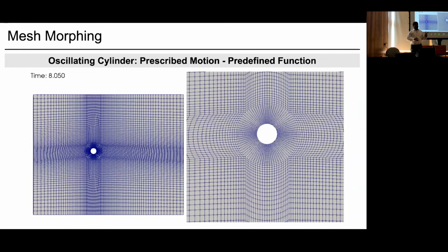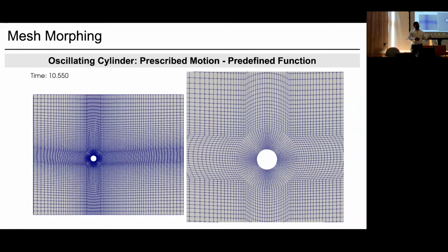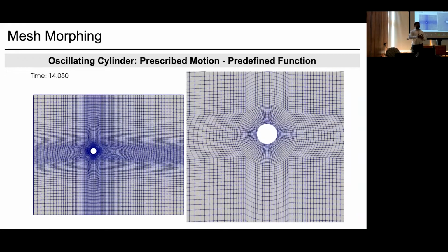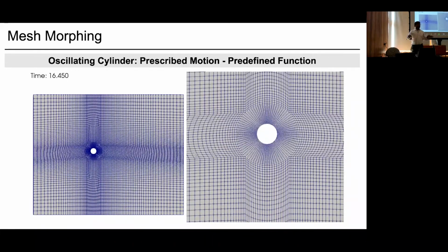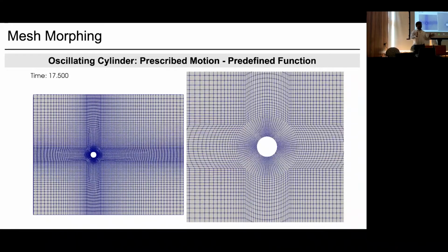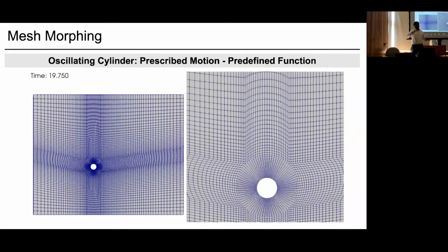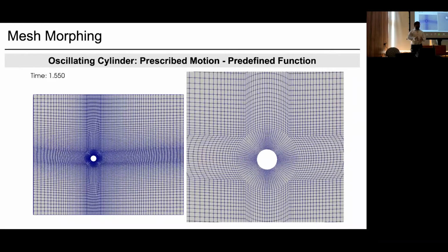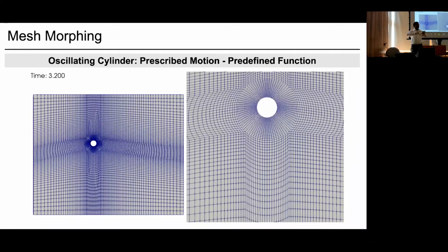Basically there are two solutions for that. I'll give another example which takes your situation. Let's say you want to simulate a 6 degrees of freedom rigid body motion of a falling body, which is unconstrained. There is no constraint and it can rotate and displace in 6 directions. If you want to simulate that problem using mesh morphing, it's very challenging, right? At a certain point, the mesh will be stretched and then it will fail.